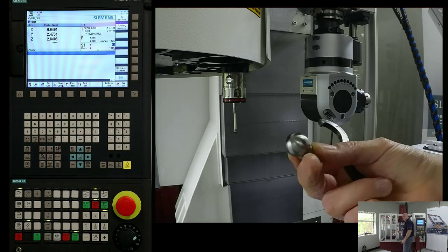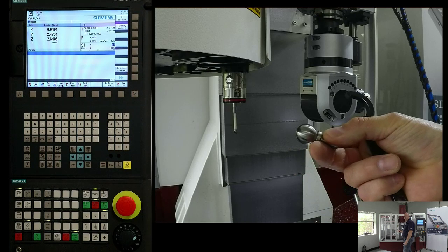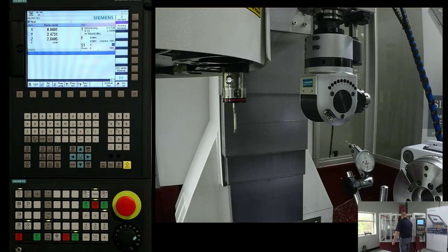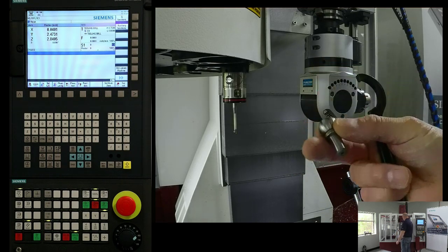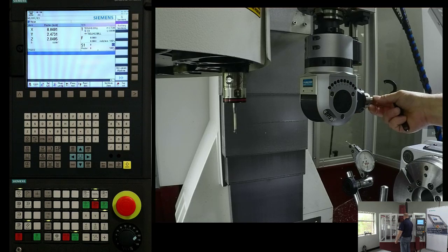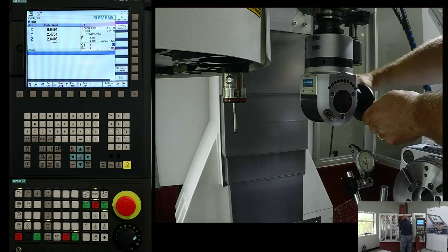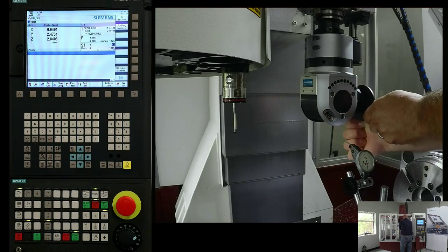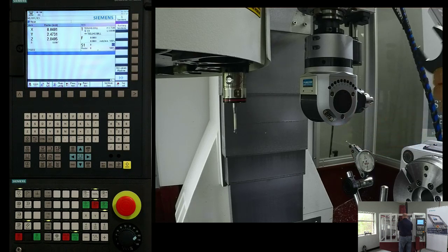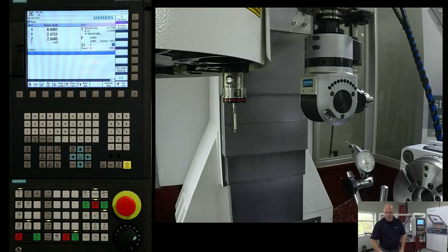So just to show you guys, this is a standard 3/4 inch diameter tooling ball that I'm using. And what we'll be able to do is actually rotate around this ball and verify that our function is tracking properly. So we're going to swap out the ball right now. We're going to need it in a little bit, so I might as well swap it out while I'm in a horizontal orientation or a 90-degree orientation.